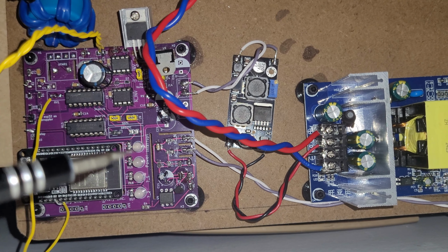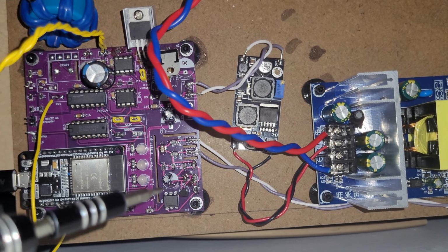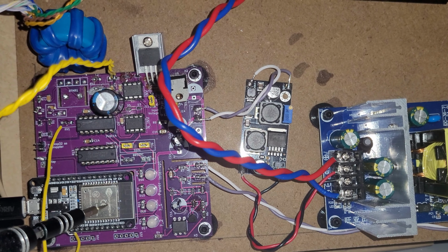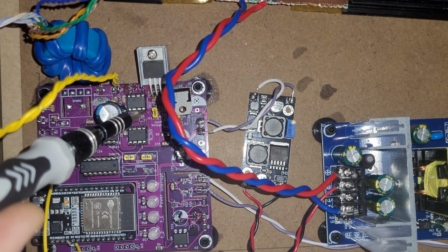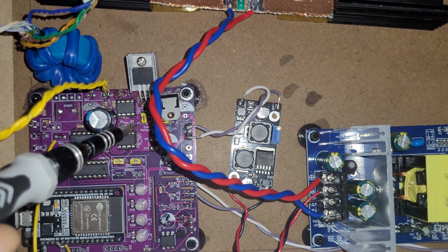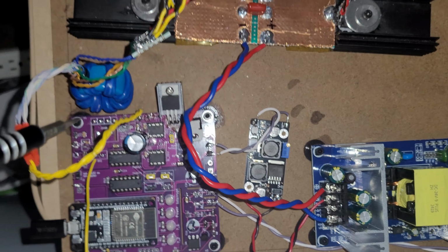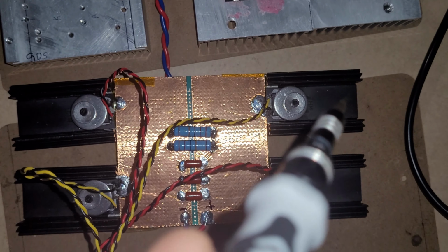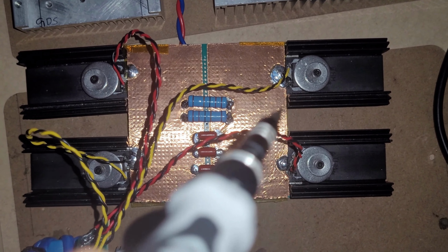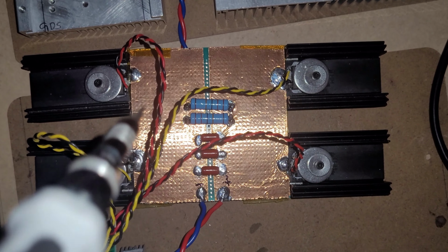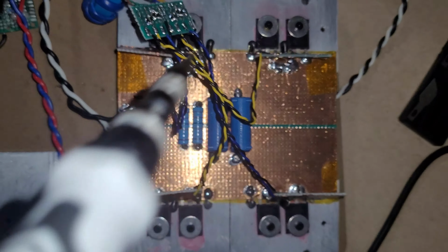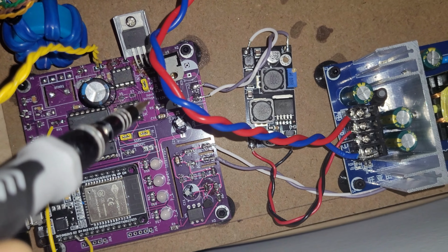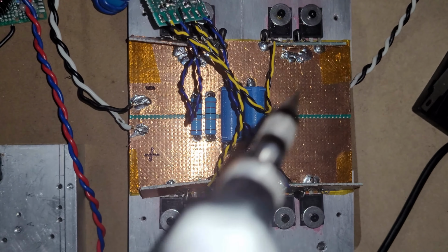So here's the circuitry that we just talked about. I'm not using most of it. I'm just using the ESP32 and the 2 gate driver chips here and here. The output of the gate driver chips goes into the GDT here, and the output of the GDT goes into the H-bridge. This is a MOSFET H-bridge. I'm using this MOSFET H-bridge to drive this IGBT H-bridge because these 2 gate driver chips are not powerful enough to drive this IGBT H-bridge directly.